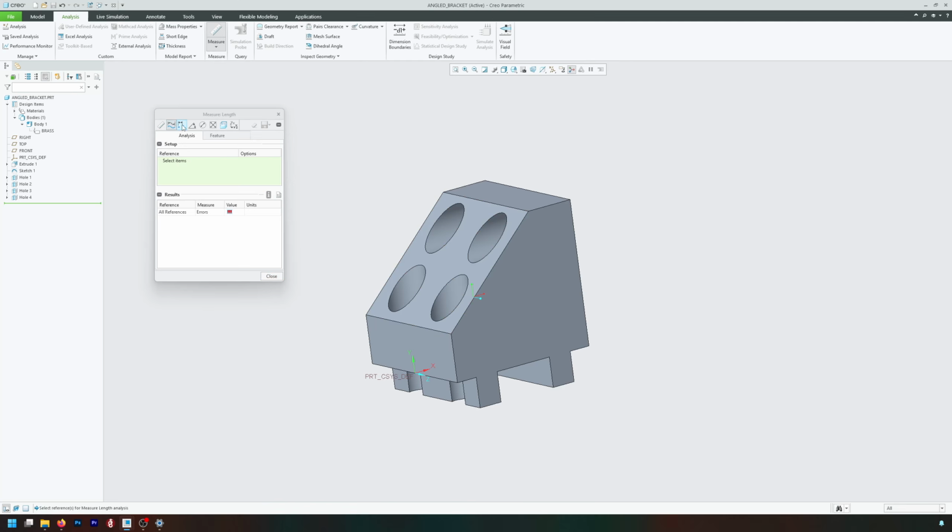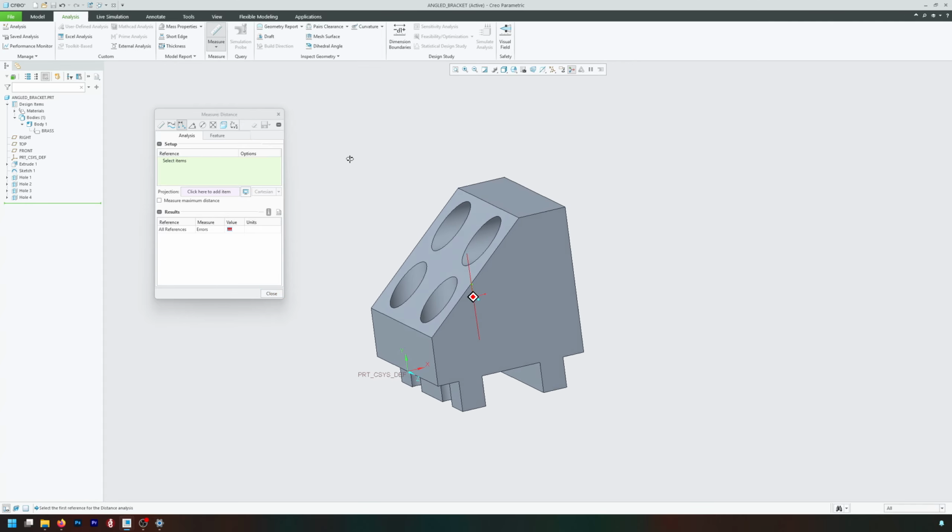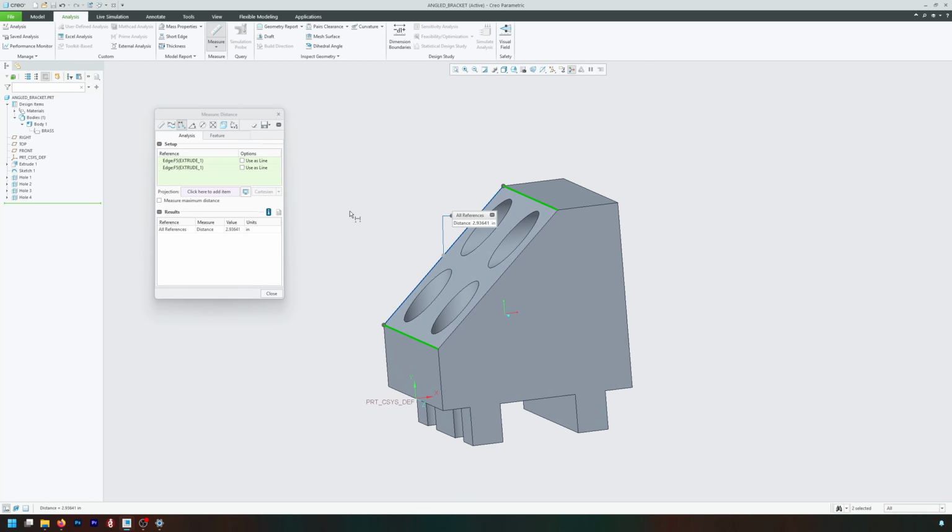Let's go ahead and navigate over to distance. All right, so this one is an interesting one. Distance, okay, what's up with that? So with distance, let's say that we want the distance between this edge here and this edge here, okay? All right, that should be easy, right? So click that edge there, hold the control key, and then click that edge there. And boom, it gives you a distance, right? Yay, how exciting, right? Well, maybe that's not what I want.